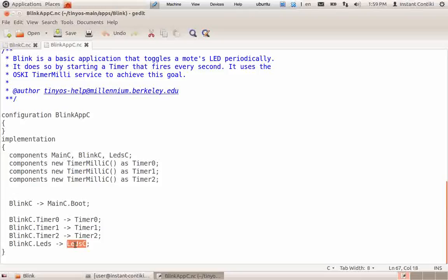Exactly. So you can build an application. For example, imagine an application that senses temperature, okay? So it will use, for example, an interface which just reads, okay? And it will use a component of the operating system that connects to this interface, and the actual component implements this temperature reading. Now you want to change the sensor, you want to use, I don't know, a pressure sensor, but you don't want to change your application. So you will use the same interface, you will just connect the read interface not to the temperature component but to the pressure component. Okay?